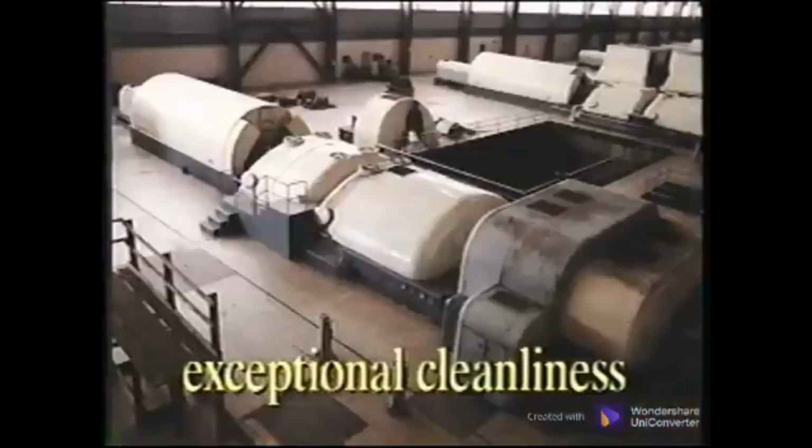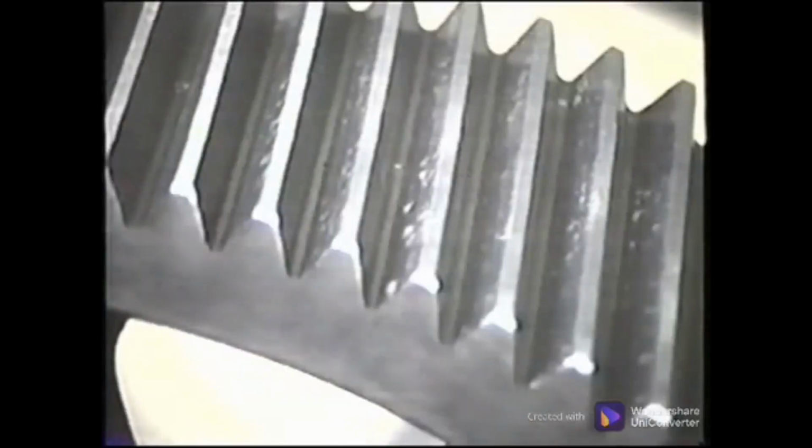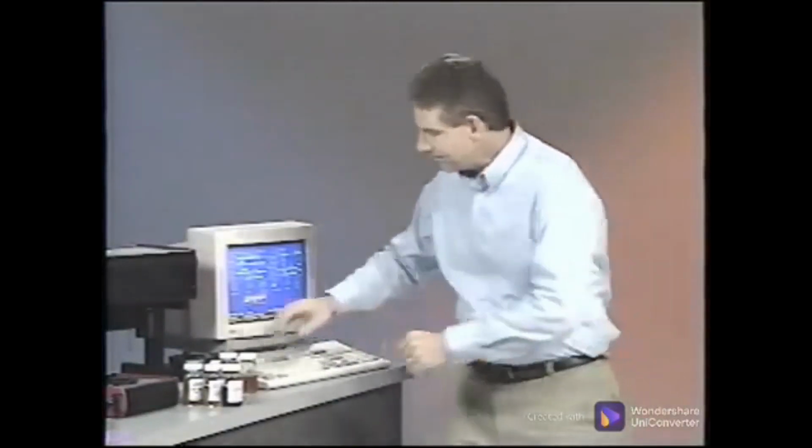Various systems and applications require different lube conditions, such as hydraulic systems and machine tooling, which require exceptional cleanliness, and gearboxes, which by their very nature tend to produce more wear. These applications require particular oils and additives, especially suited to the demands of the system, and should have different standards of cleanliness. The most important parameter of a lubricant is the viscosity.